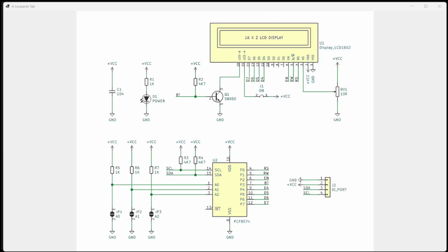And then here is the connector, and as you see, we're using four. So I'll bring the pointer over here so you can see it. We're using 4 data bits. This is the power jumper, like I say, LED anode connects to that, or you can connect another power supply. If you're driving one of these things on 3.3 volts, you might want to connect a 5 volt power supply. You might just want to use a different power supply.